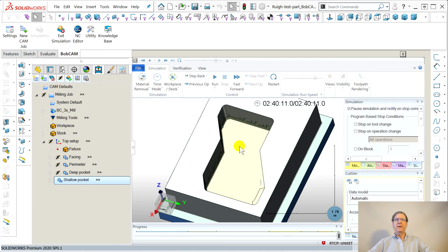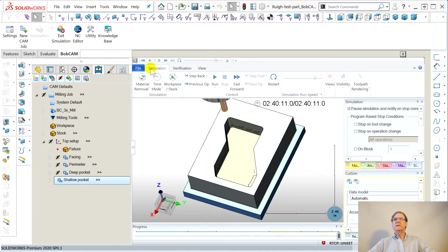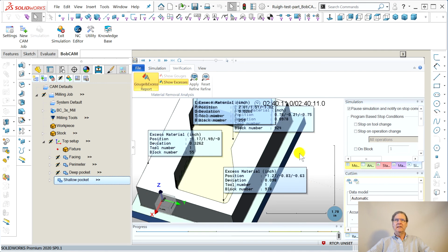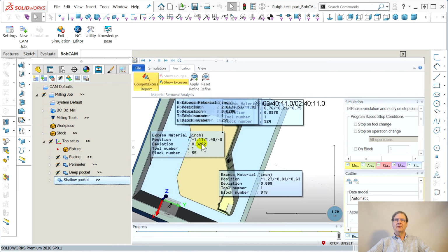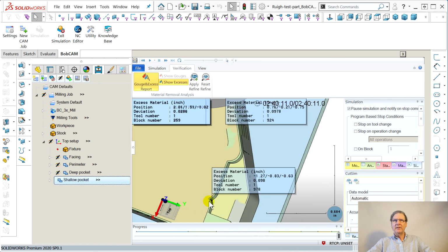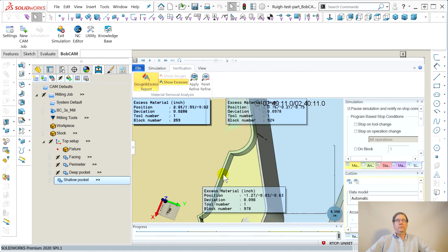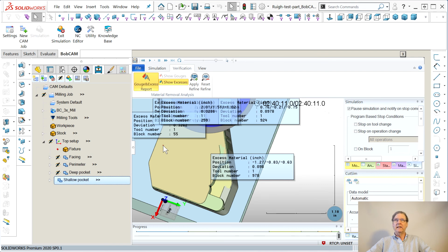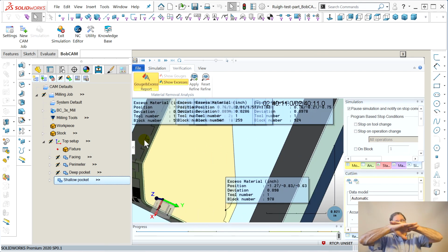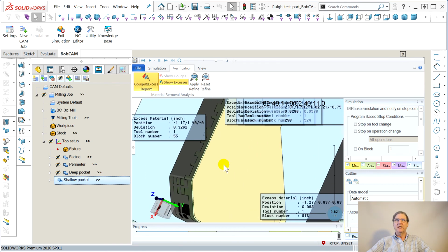Visibility, hide the toolpaths, go back, do this verification business, say gouge and excess. It thinks for a while, show excesses, and now it's got this stuff. See, it does funny things too, like it leaves little color changes here and here and here, and what is that? I think they're non-existent, just a rounding error in the math where, okay, we think we're on that surface. Well, it might be that surface, and that kind of stuff changes.